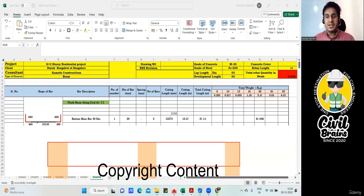So what is the total cutting length we got? It is 13.570. So 13.570 is the total cutting length that I require. So my one bar will start from here. I'll go with the bottom bar only. So at the bottom, you'll start here. Your development length will start here. I'll take a bigger one.